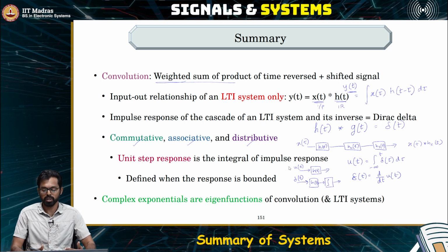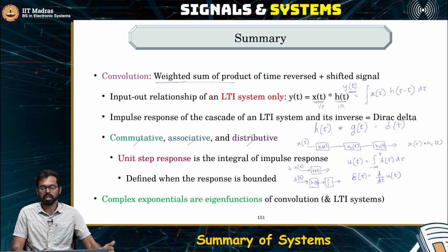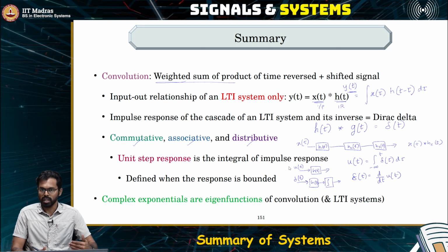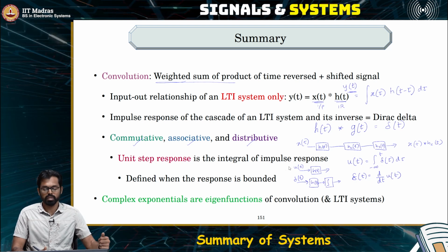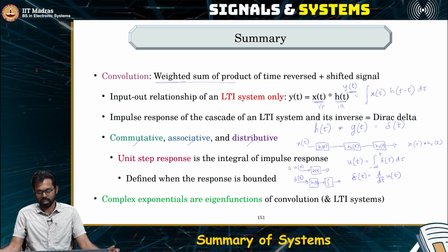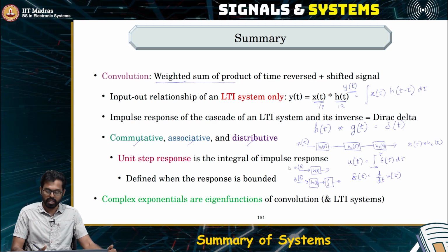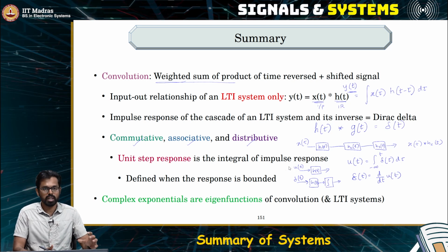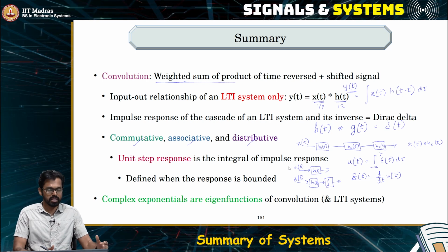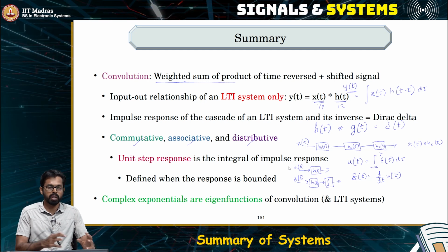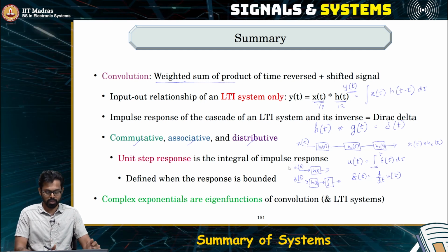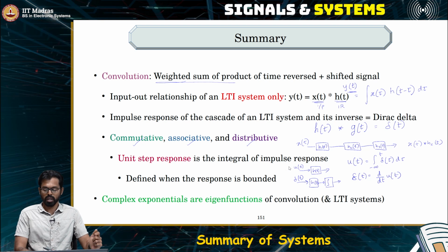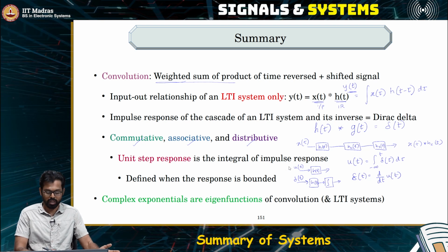Then we will not be able to know what was the signal that was actually fed to this integrator. You can feed in 1 or you can feed in 10. For both you will get infinity as the output from this integrator. So the integrator is actually becoming unstable for certain inputs. Whenever you feed in these inputs, the integrator is unstable and you will not be able to invert back for these inputs. So for this reason, the integrator becomes unstable and not invertible.